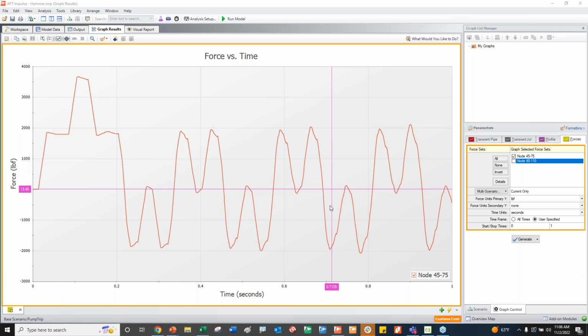Would you say that response spectrum analysis versus time history analysis will tend to overestimate dynamic forces for shock loads, as per your example? I think that time history analysis is more accurate, and now that we have the computer capability, it's worth doing. But spectrum analysis has been useful all the time, so it really depends on your criteria whether to use one or the other.